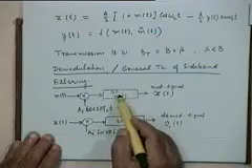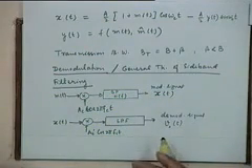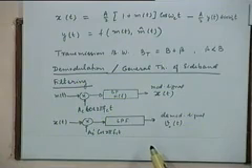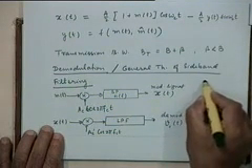So what kind of filter transfer function should this be? Suppose you want the upper sideband, so maybe this could be a high pass filter, but with some specific requirements. What should be the nature of H(f) so that v_o(t) is proportional to m(t)? That is the question.